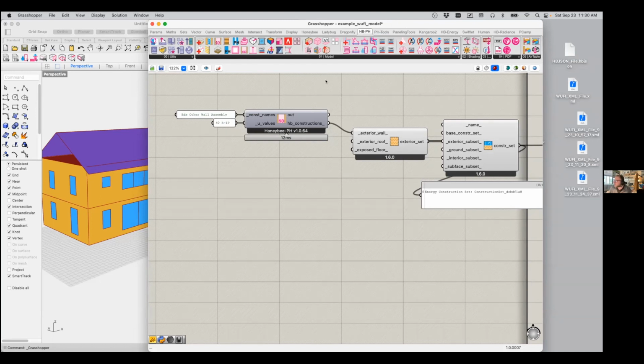So for our purposes here, though, let's carry on with our optimization work. So we were saying, oh, we got down to like 22 or 25 kBTU per square foot per year. That's pretty good. But we have some other assemblies that we should probably set. So maybe we should set our exterior wall in this case.